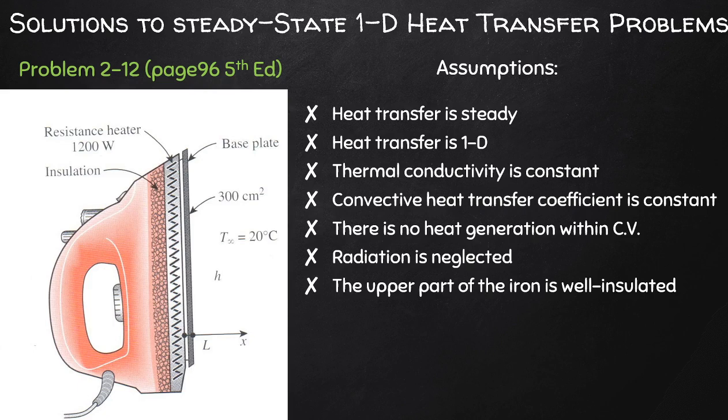Also, we are told that radiation is to be neglected, as stated in the problem statement, although this may not actually be a very good assumption to be making. So just be careful. Sometimes you'll see in the textbook that it does this, but personally I would not have neglected radiation because we work with very high temperatures, and we also end up with very high temperatures to begin with, which are maybe not applicable to this problem. Okay, we're also told to treat insulation as being ideal. Okay, so heat transfers only in one direction, from left to right in this case.